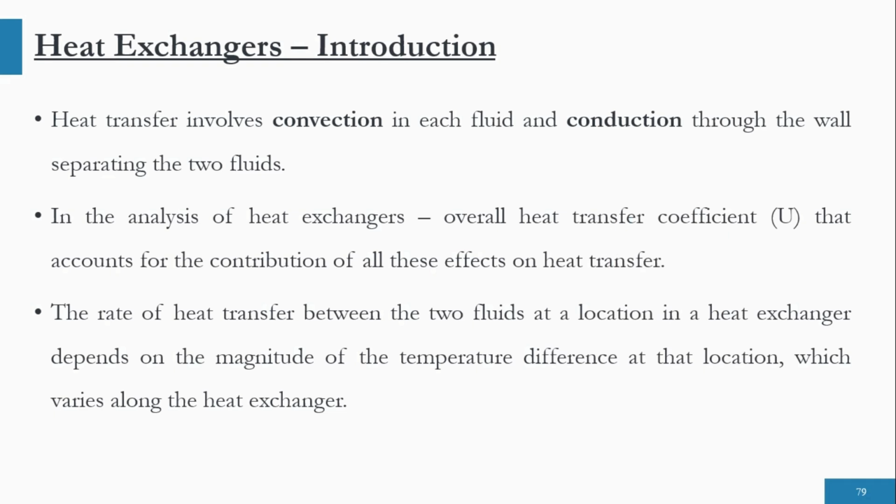Let me show you: if the cold fluid is coming here and the hot fluid is going here, then at each point the magnitude of the temperature difference between the hot and cold fluid will dictate the rate of heat transfer. The more the temperature difference, the more the heat transfer. We have already studied that in our previous lectures. This is the overall introduction of heat exchangers in today's lecture.